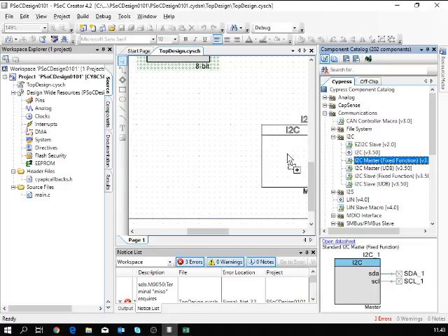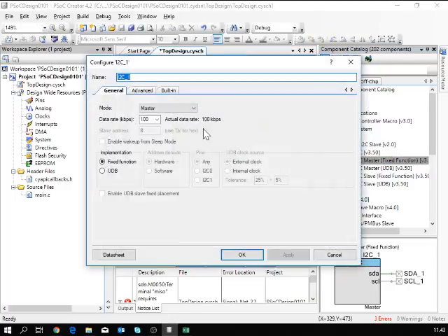Basically, if you use the fixed function, then you click the data rate here. If you use the UDB, you can actually route a separate clock signal there. But I think the fixed function master is easier to use. And this is fun: there's a selection to change this one to UDB. So practically they are still the same design. Okay, so that's the I2C.